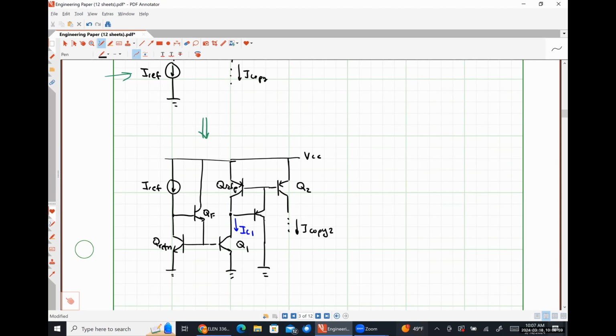So I have a homework problem that I'm going to ask you guys to work to find the error in a system like this. I'm telling you explicitly, break the problem up into two stages. Figure out what's going on with the NPN stage first, and then just treat that like a current source, and then do the analysis on the PNP side. If you try to do it all in one go, it's going to get terrifyingly gross with all of the algebra that it entails. This is realistically what a good PNP current mirror would look like.